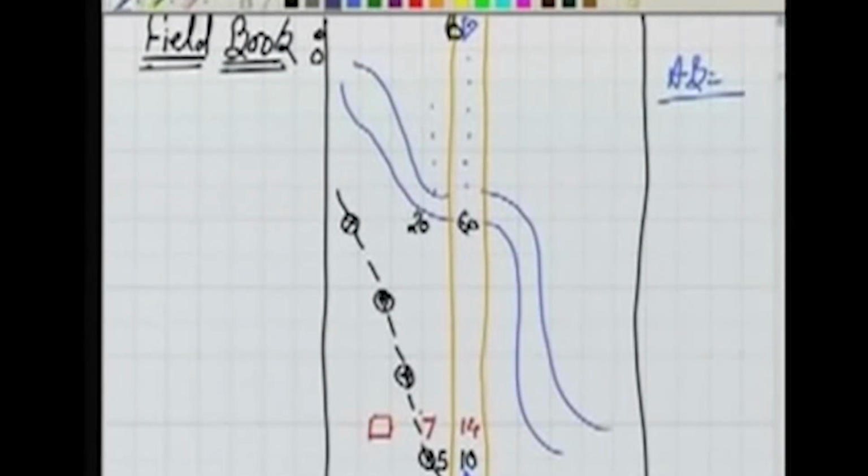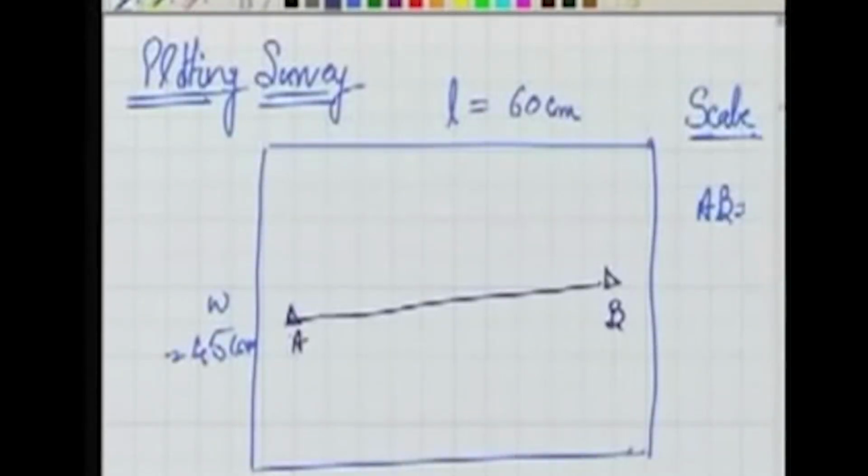I observe in my field book, well, moving from A to B at a distance of 10 chainage, there is an offset of 5 meter, which is for a telephone pole. So I do plot this. Going from A to B at a distance of 10 meter, I can measure 10 meter here. We have a perpendicular offset at 5 meter, and that is for a telephone pole.